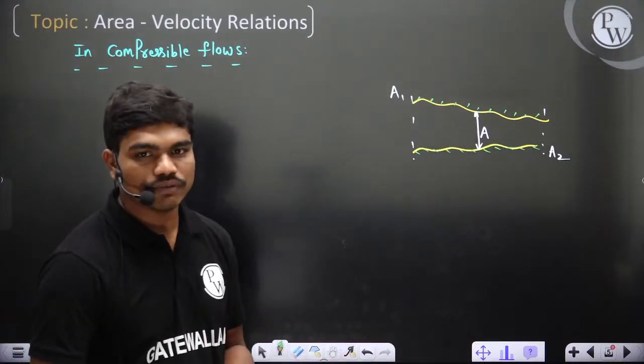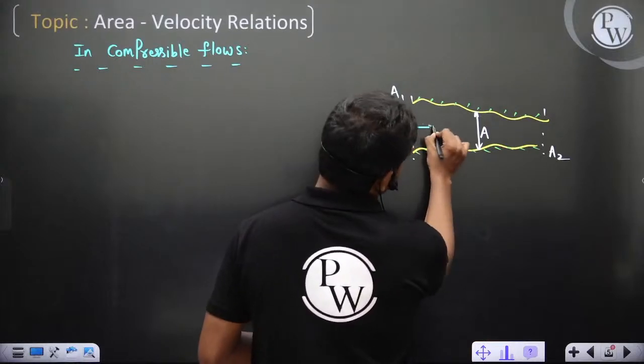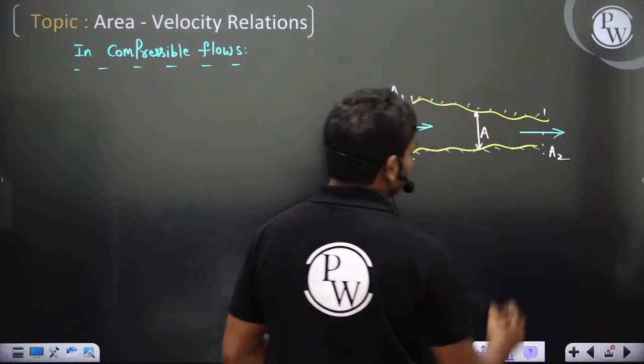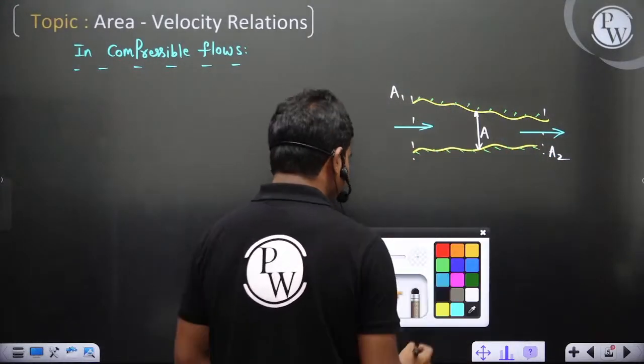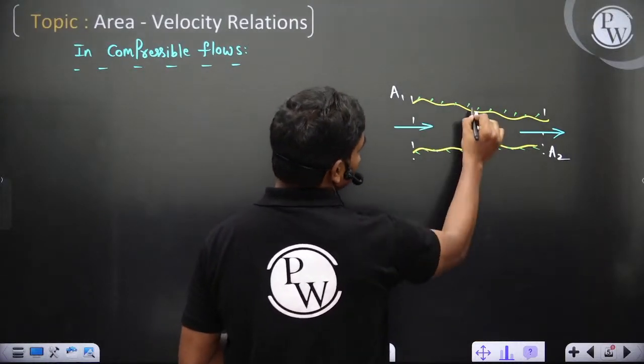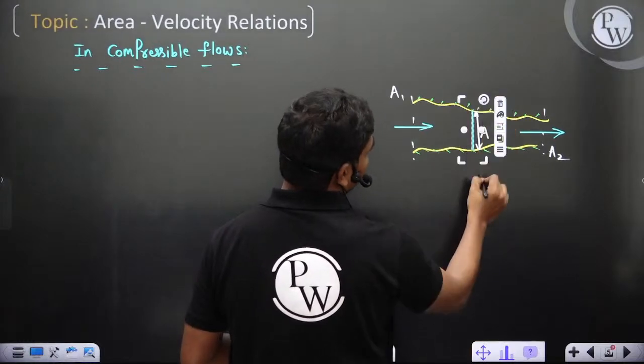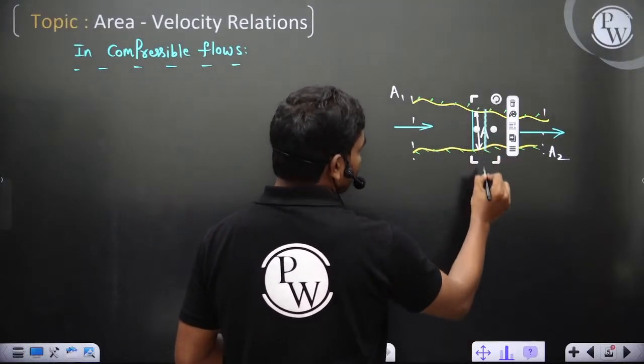Good evening, Rexo. Okay, so see here, let's say the fluid enters like this and it flows over this cross section, then it flows over this passage. You take a small section of length dx along the length of the nozzle to analyze what happens to the fluid velocity.